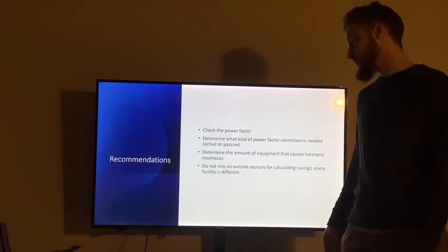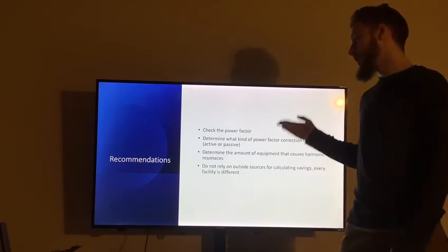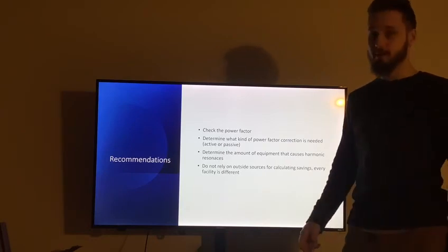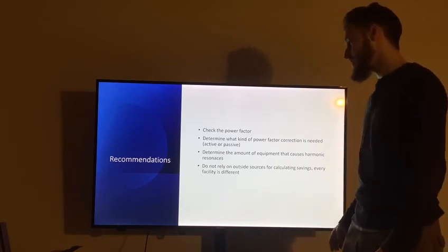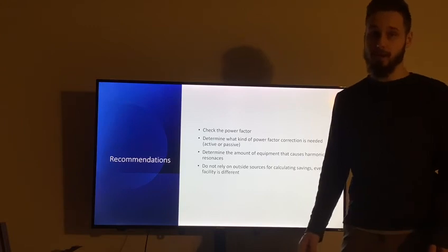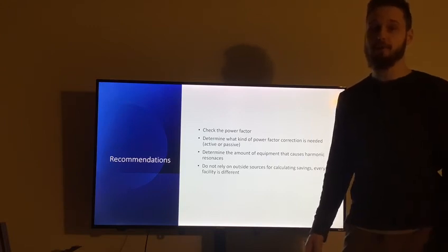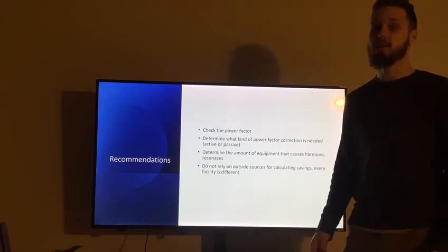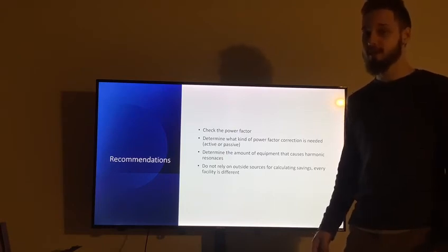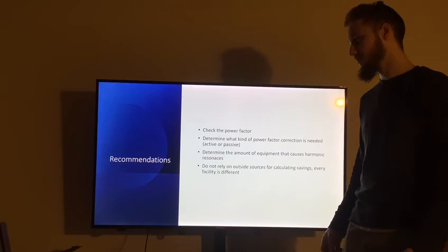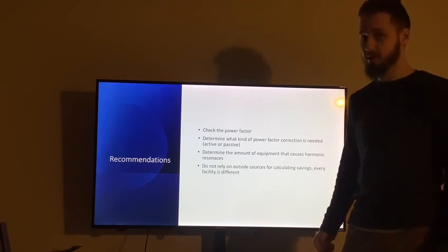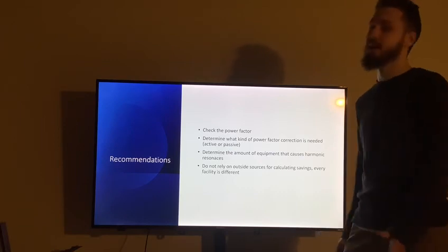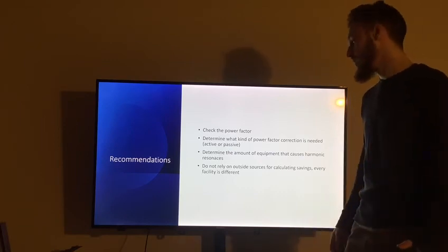So, recommendations. First, check the power factor to see if power factor correction is necessary. Next, determine what kind of power factor correction is necessary, active power factor correction or passive power factor correction. In facilities where the inductive loads are changing, you will need active power factor correction. If the inductive loads are on or off type, then you will need passive power factor correction.